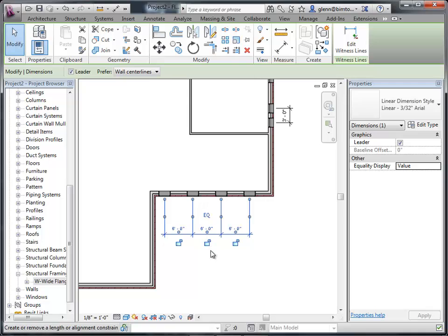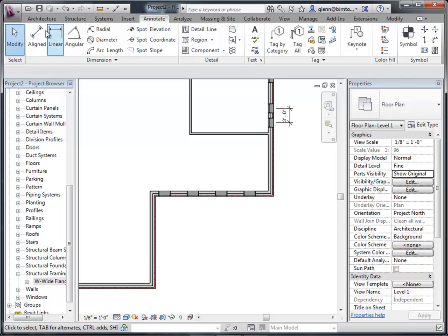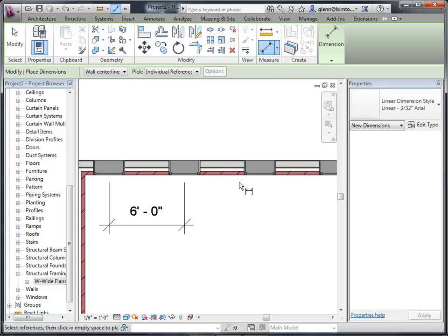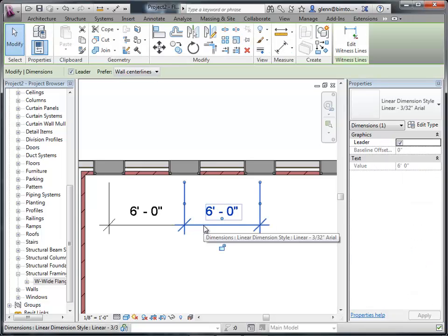Okay. So again, if you do that, let me unconstrain it right now. If I did it as a series of separate ones, it wouldn't be there. For example, here to here, and then here, just zoom in. We'll get to a question here in a second. Okay, those look like a string of dimensions, but they're not really. That's actually two different dimensions. So at this point, the EQ is not available because I define them as two separate relationships.